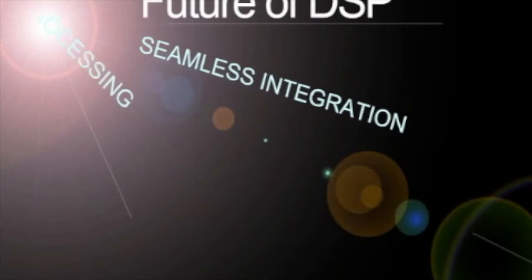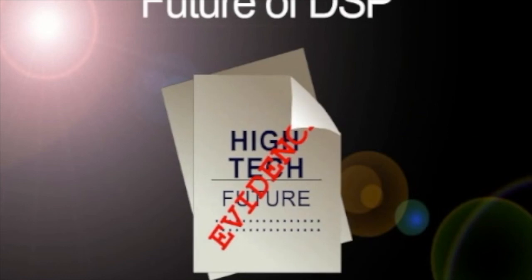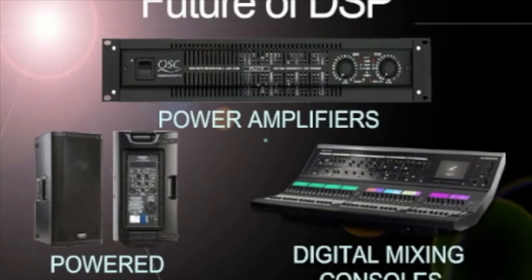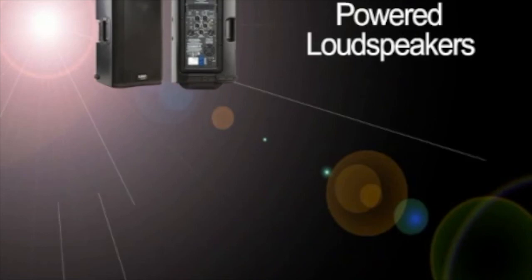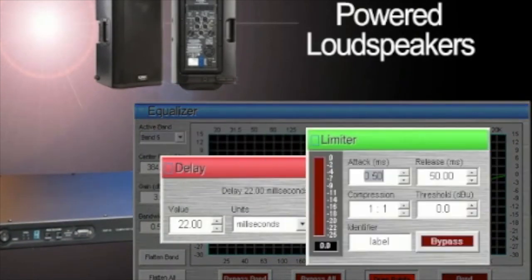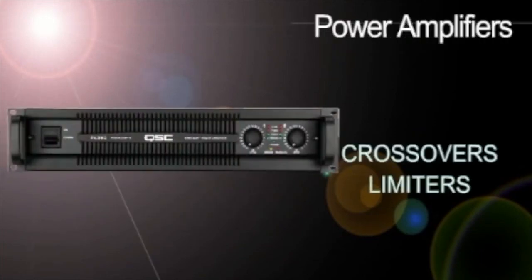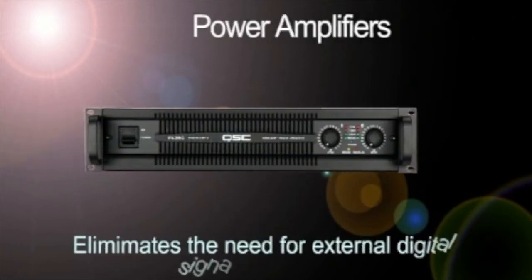The future of DSP technology will provide seamless integration of device-specific processing incorporated into the digital device. Evidence of this is beginning to surface in newly developed powered loudspeakers, power amplifiers, and digital mixing consoles. Powered loudspeakers will have built-in equalization, delay, and limiting, all controllable via the network. Digital mixing consoles host all of the signal and effects processors needed to mix. Power amplifiers have crossovers, limiters, delay, and equalization built into the unit, which eliminates the need for external digital signal processors.